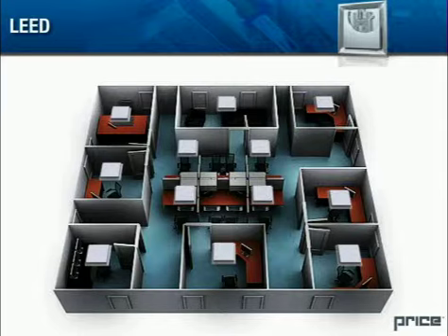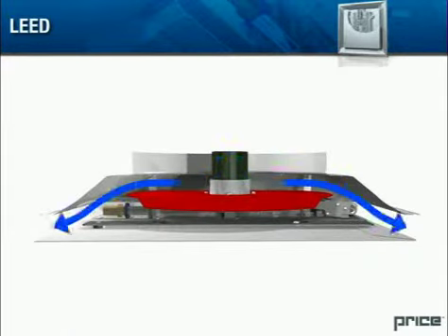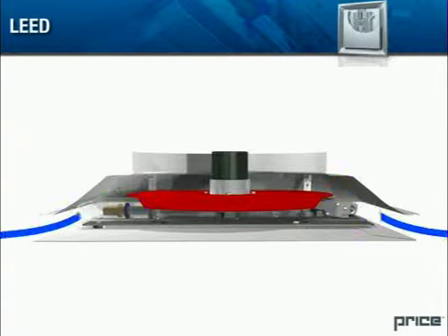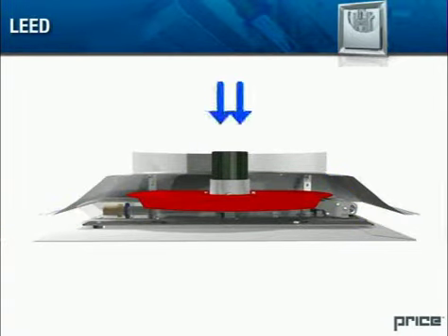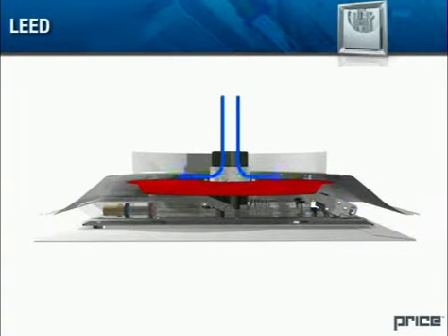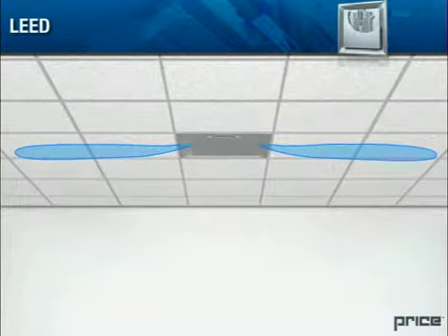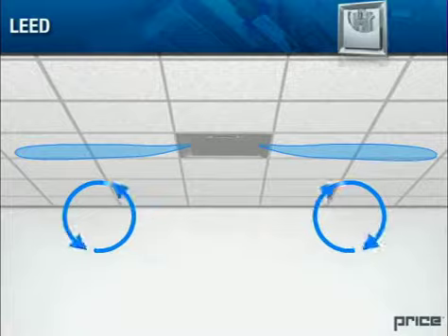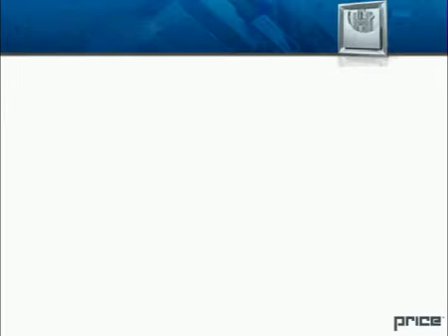Thermal comfort. When designing an overhead air distribution system, the location of air outlets must be carefully considered to prevent drafts. With Price's VAV diffusers, supply air is maintained at a high discharge velocity, even at very low flows. This ensures that the Coanda effect is maintained, dumping is avoided, even mixing occurs, and personal comfort is assured. We'll examine this further in the upcoming section.